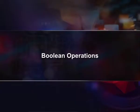Let us move on to Boolean operations. In Maya, a Boolean is an operation that is performed on 2 objects to create a single compound object. You can apply 3 different types of Boolean operations: union, difference and intersection. These objects must be overlapping or intersecting in some way. To select multiple objects or components, hold Shift and left mouse button and click.